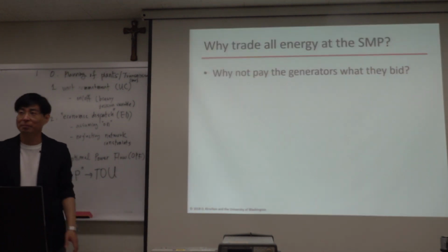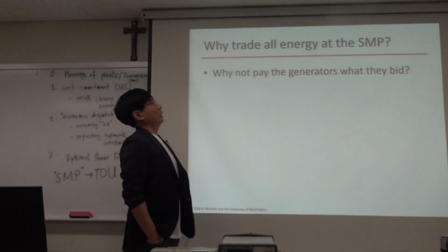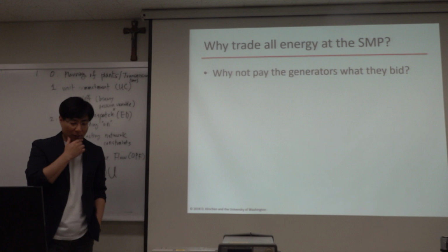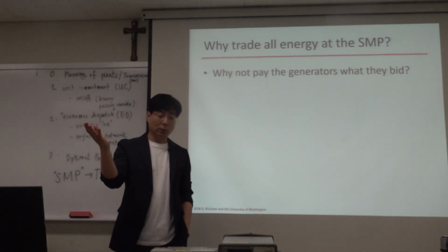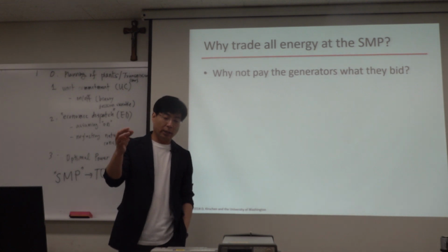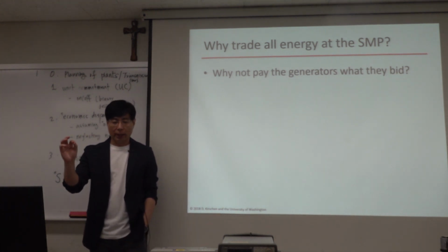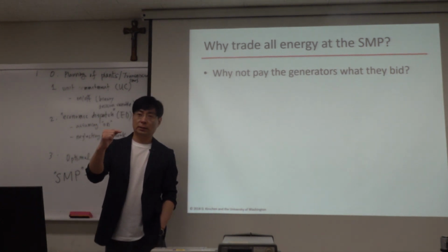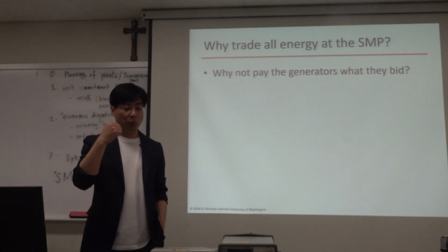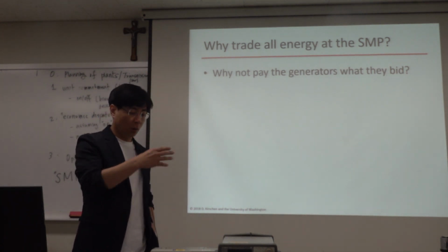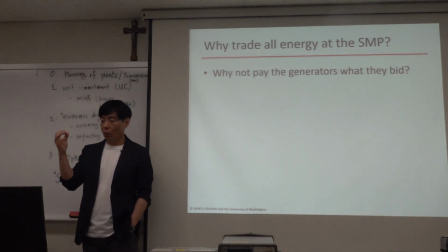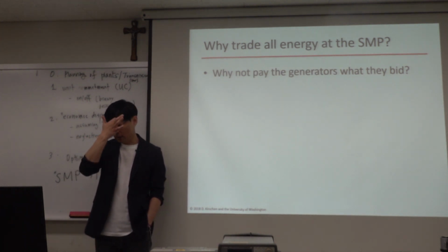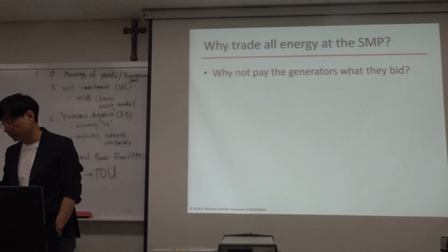So maybe this is the last slide. Why do we need to trade all energy at the same SMP? To make a long story short, if we ignore the startup cost and the fixed cost and just consider economic dispatch, then using a single price, SMP, to pay all the generators is the one that minimizes the total generation cost. That is from a simple convex optimization problem solution.